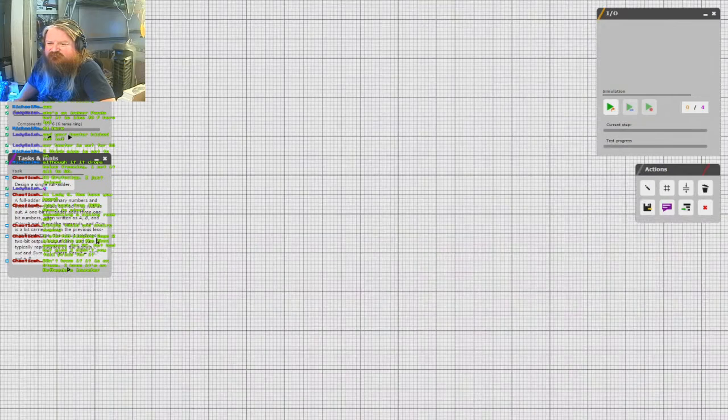The circuit produces a 2-bit output, carry and sum, typically represented by the signals C out and sum, or S. Result equals 2 times C out plus S.